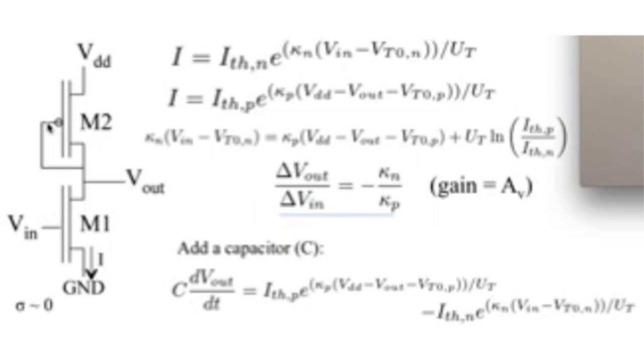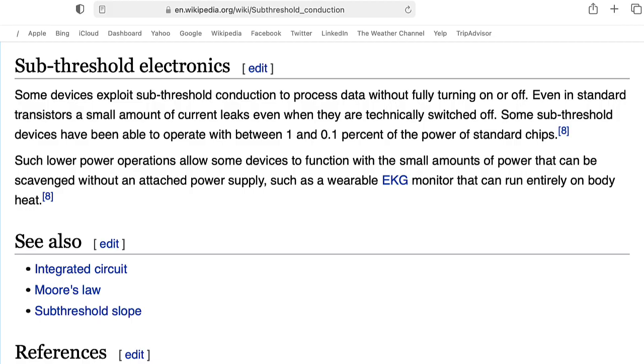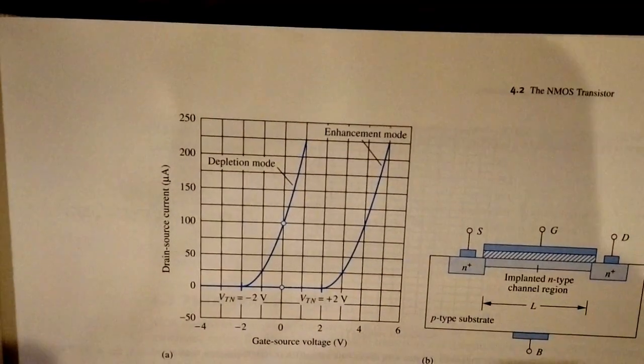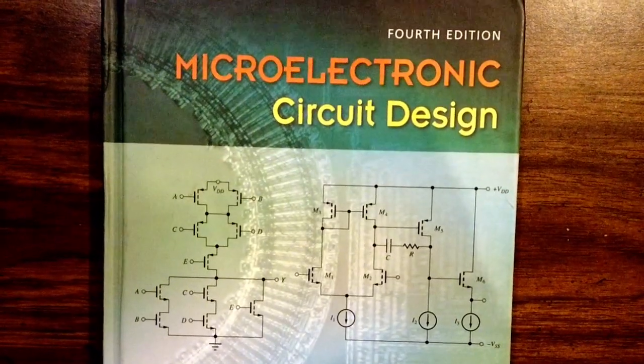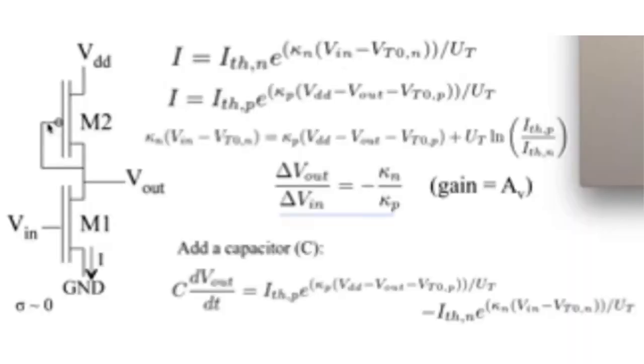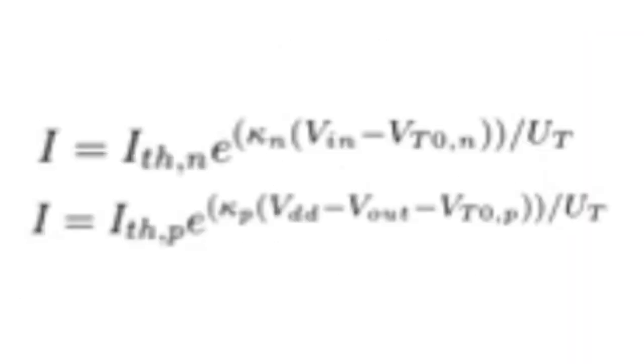These might look a little strange for MOSFETs that are usually written in terms of a square law, but Professor Hassler likes to operate her MOSFETs in the subthreshold region, which a lot of textbooks just call off. Those textbooks will assume that no current is flowing in that subthreshold region, although in reality there is current flowing according to these exponential laws.